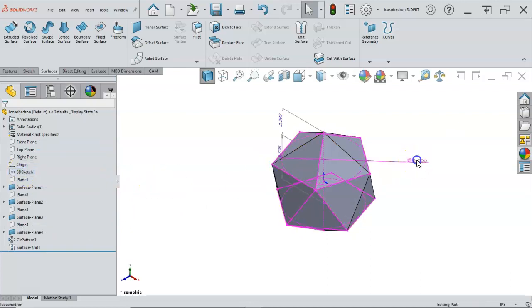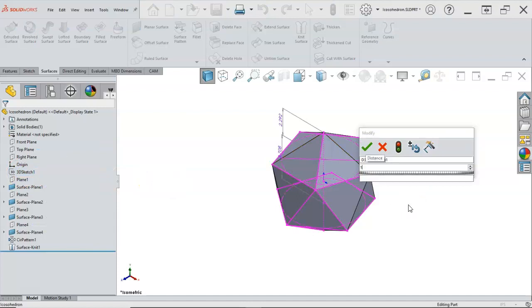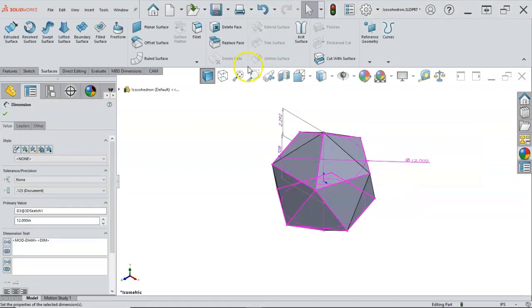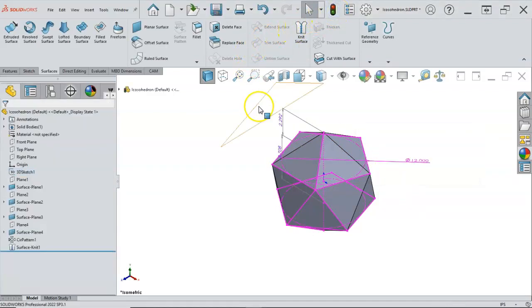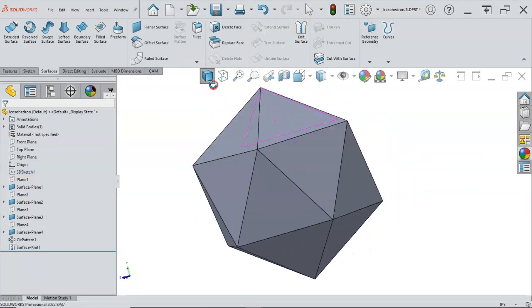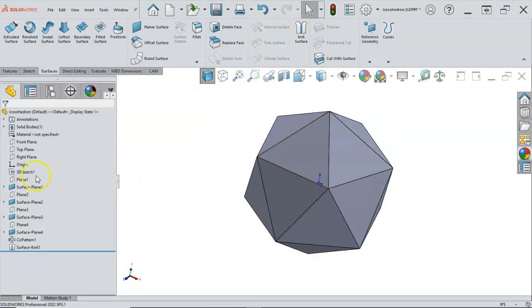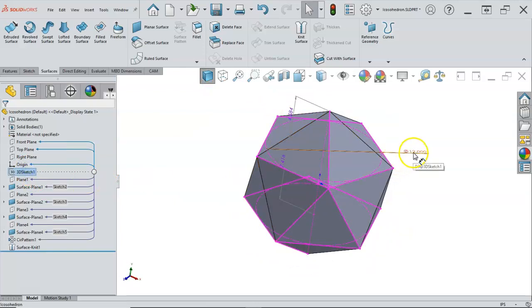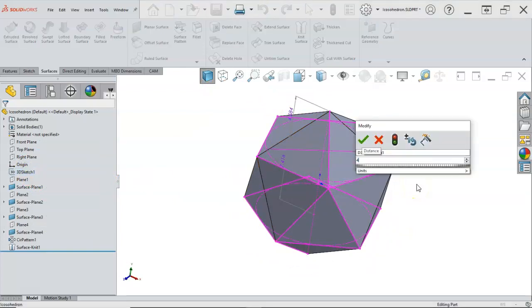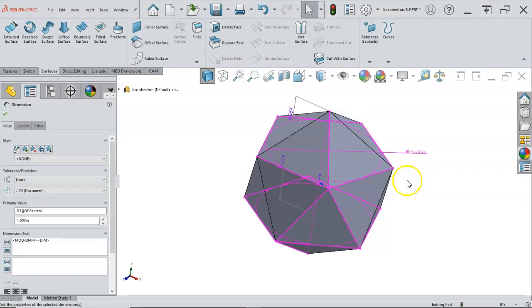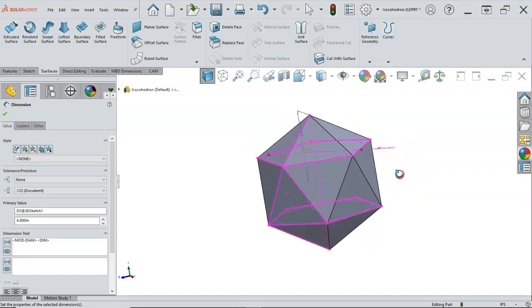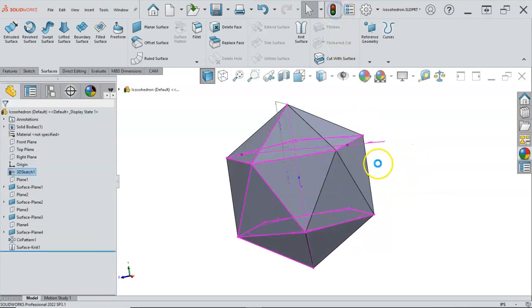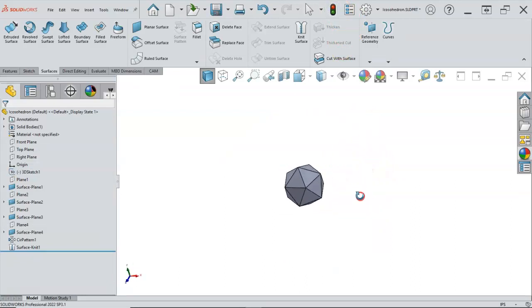So the other check real quick is if I wanted to make this a 12-inch. Then I change the value, hit rebuild, and the icosahedron is going to go to the next size. For machining, realistically, I don't want this much over 4-inch. I'd really need to see what kind of cylinder this would fit into, because I think I would be looking at holding this in a 3-jaw or 4-jaw chuck, so that when I machine it, there is a post or something at the very end.